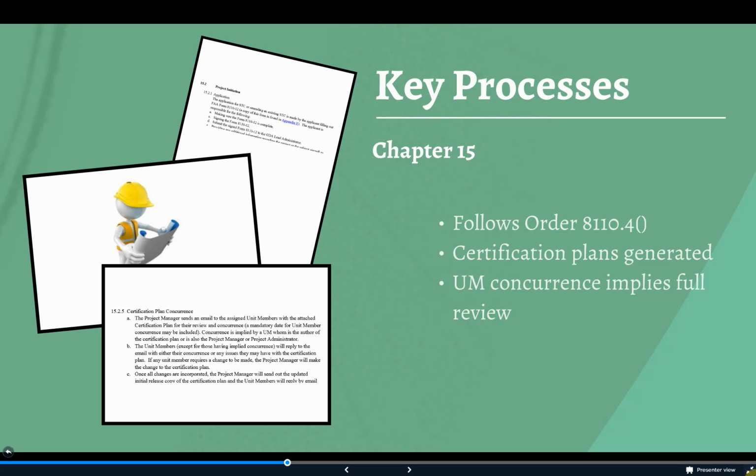When a project is first initiated, this manual change added a step to have the OLA review submitted applications and determine if a project is substantial or significant using FAA Order 8100.48. It also refers the reader to AC 21.101 for determining the certification basis.